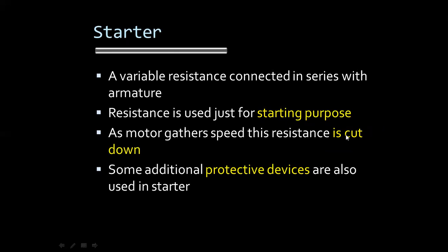It's not only the resistance which is incorporated in starter. We also have some protective devices used in starter, which can protect the motor against overload condition, which can protect the motor when supply voltage fails or supply to the motor is interrupted. So these two additional devices are incorporated in starter.